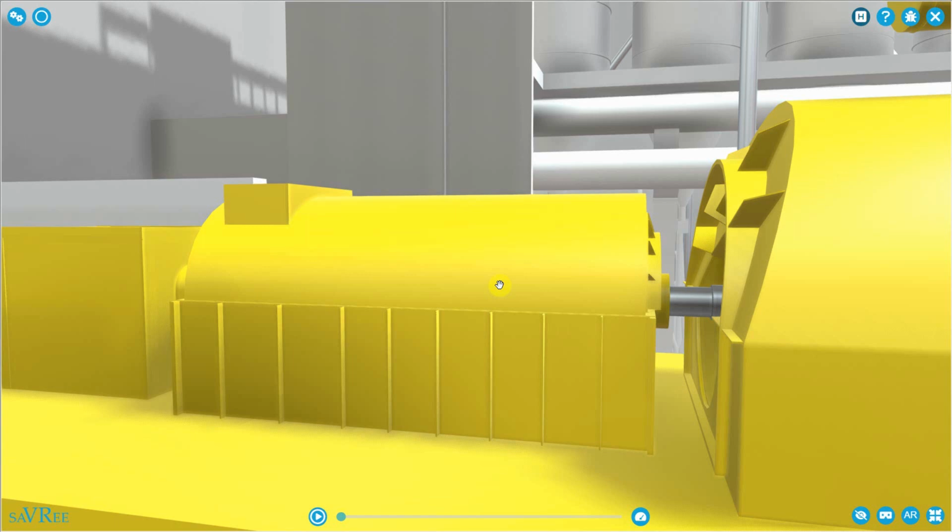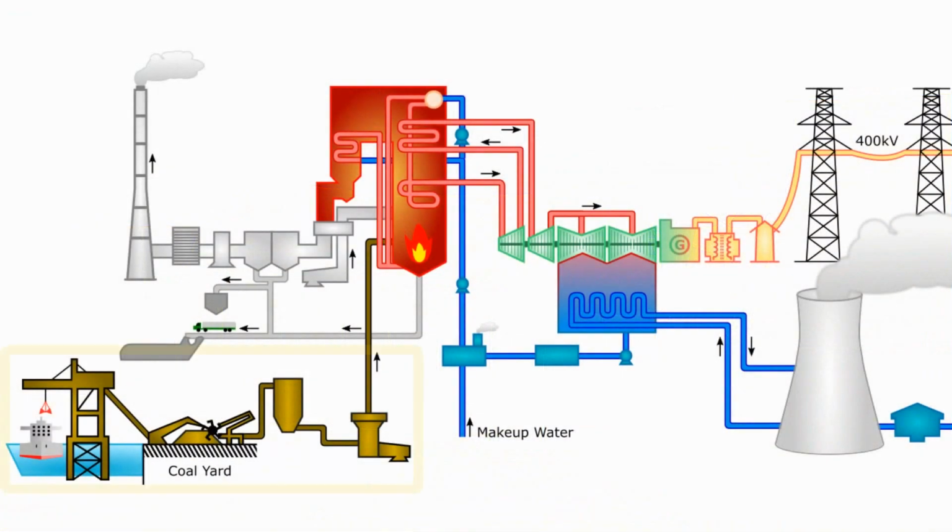Important to realise though, we're not actually producing electrical power here, we're just transferring energy from one form to another. We started with coal, which is chemical energy. We released that by burning it. We then transferred the energy to steam as heat, which is a form of kinetic energy. When particles vibrate together, we generate heat. We're then taking the energy from the steam, transferring it to our steam turbine rotors, and will cause the rotors to rotate. At this point we have mechanical energy.